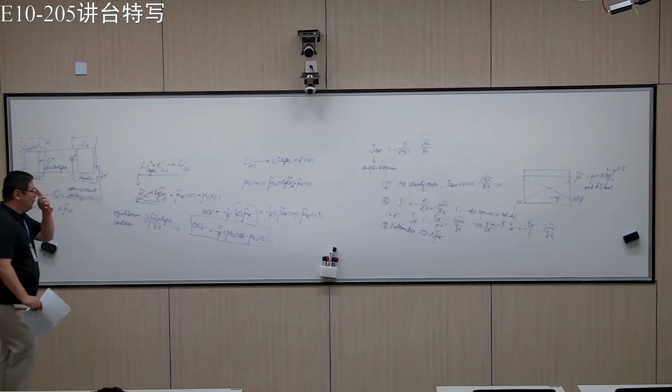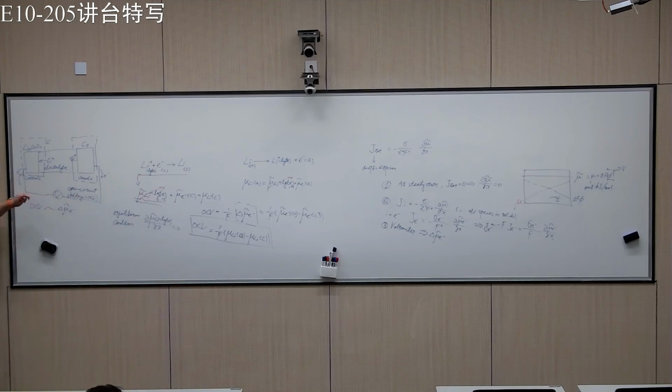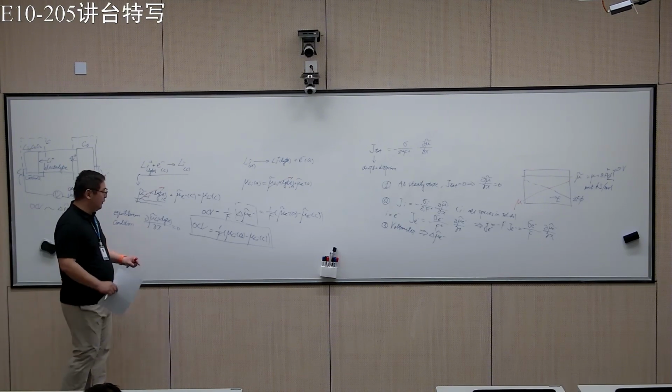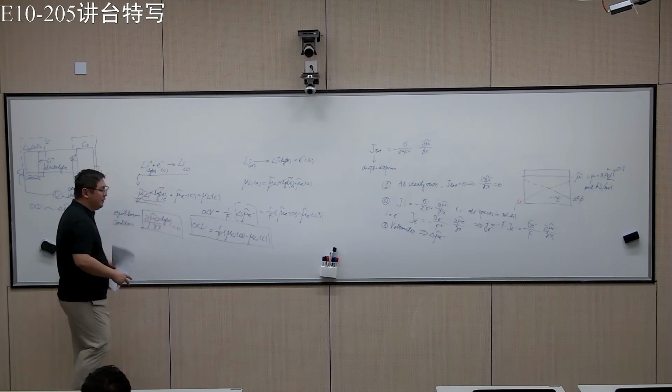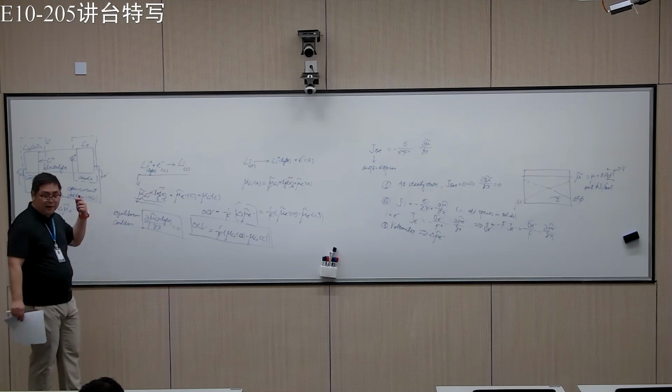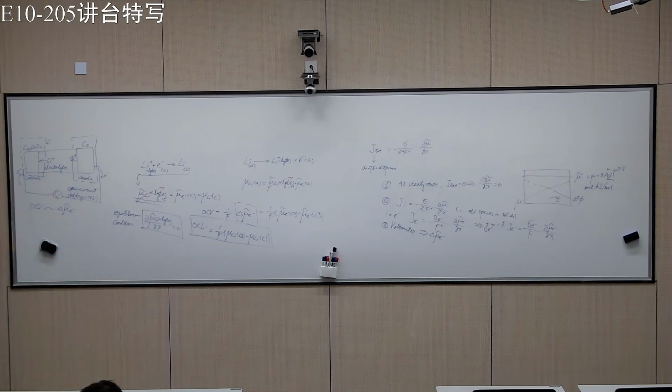So basically, what we get here is that for an electrochemical system such as the lithium-ion battery, at the equilibrium or OCV condition, there's no net transport of lithium ions. Otherwise, you'd have a current, right? Otherwise, it wouldn't be open circuit.